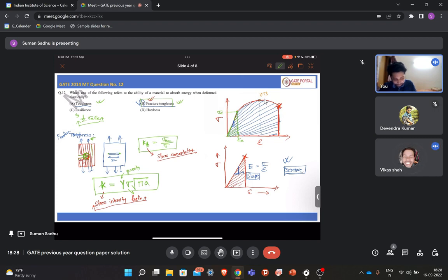Okay, and this a is the length of your crack. If it is an edge crack, let's say this is your edge crack, then this length is a. If it is a center crack, then it will be termed 2a, so this a is half of your crack length. Okay, so this is your stress intensity factor.